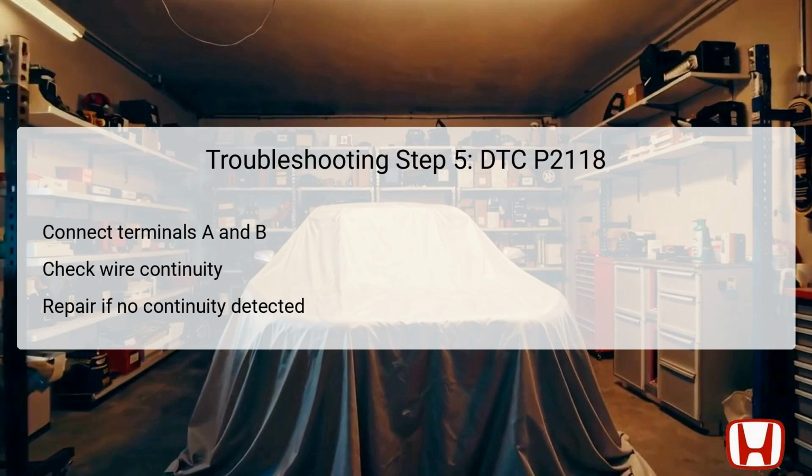Once connected, the technician should check the continuity between specific test points on the PCM connector C. This test is critical as it confirms whether the MTR1 and MTR2 wires are functioning correctly without defects. Upon finding continuity, it suggests the wires are intact, assuring that we can proceed with the diagnosis confidently.